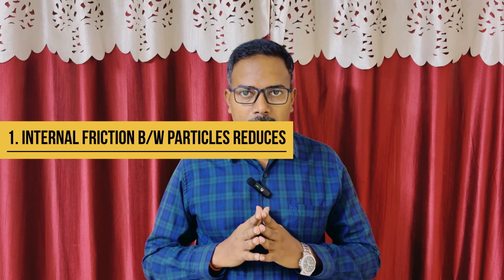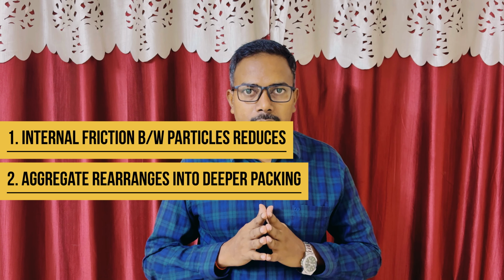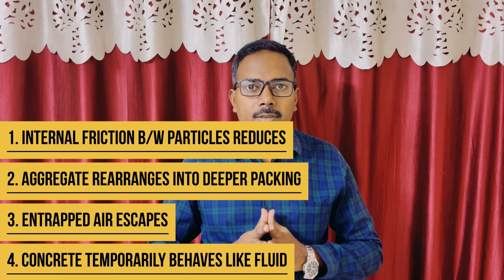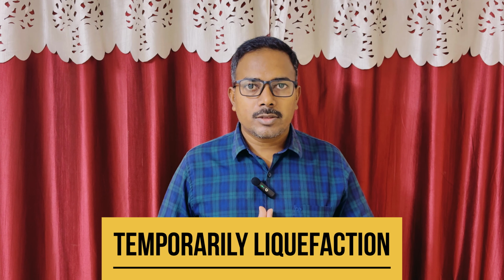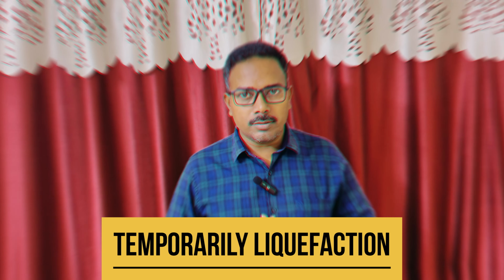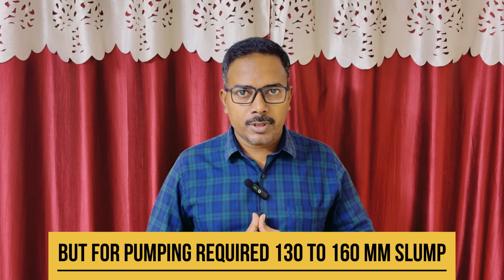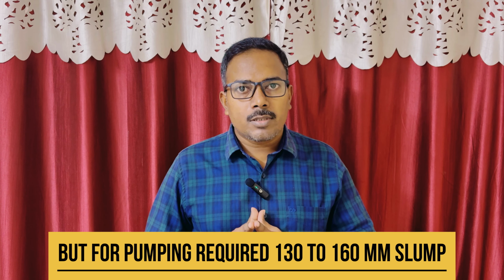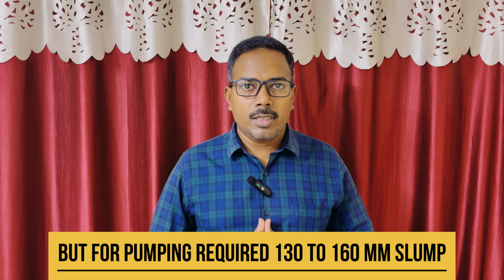What does vibration actually do? When you apply vibration in low slump concrete, internal friction between particles reduces, aggregate rearranges into a denser packing, entrapped air escapes, and concrete temporarily behaves like a fluid. Engineers call this temporary liquefaction. So even a 25 mm to 50 mm slump mix flows around reinforcements, fills corners of formwork, and achieves full compaction, because vibration provides the energy that slump doesn't. That's why low slump plus vibration equals perfectly dense concrete.